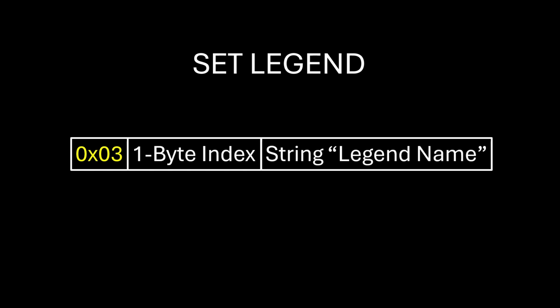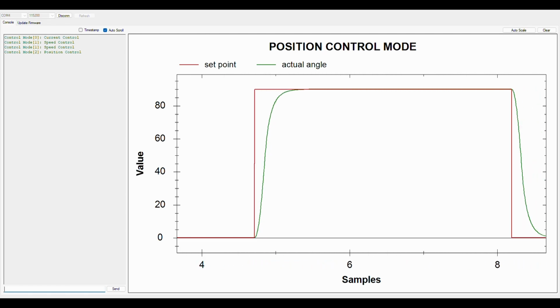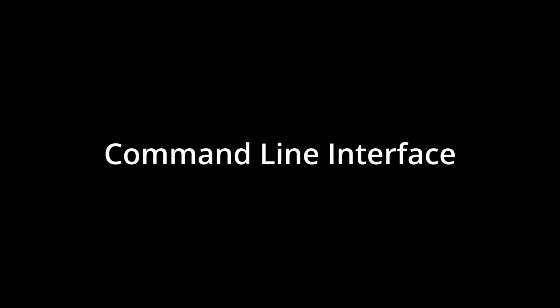To change a legend name, the first byte sent is 0x03, and the second byte specifies the index of a legend to be changed. This header is then followed by the string for the new legend name. In addition to the fast plotting feature, I also equipped this software with a command line interface or CLI.